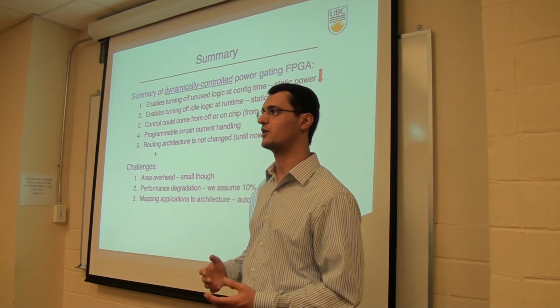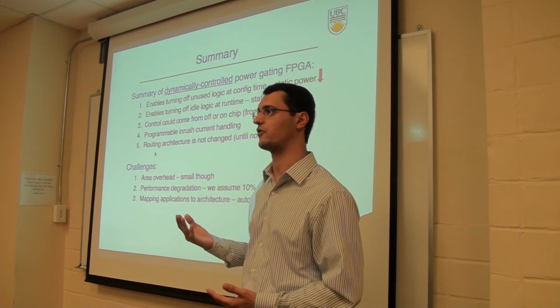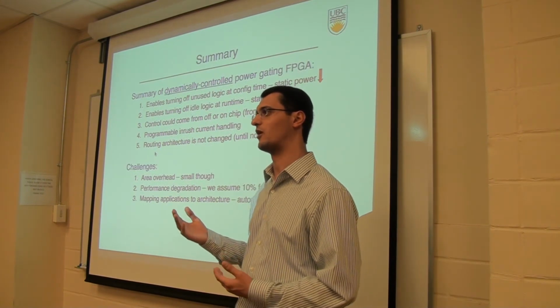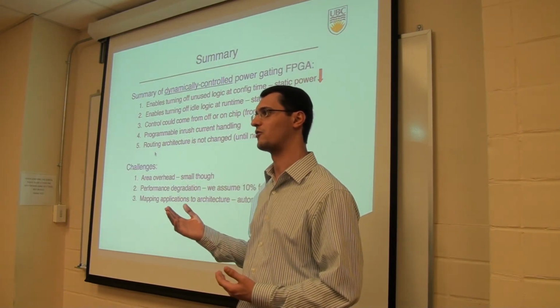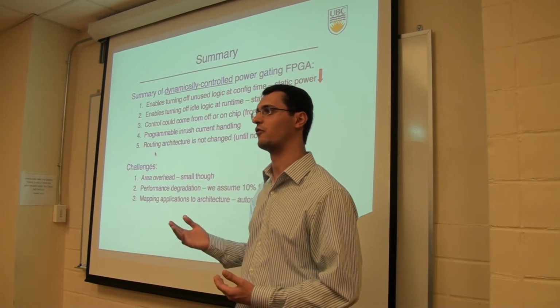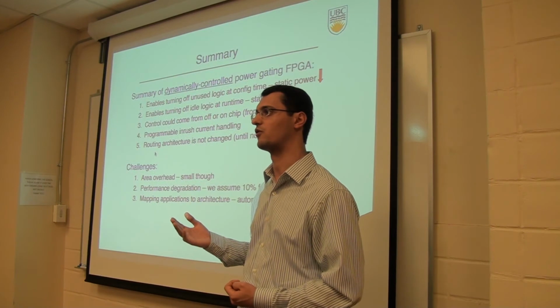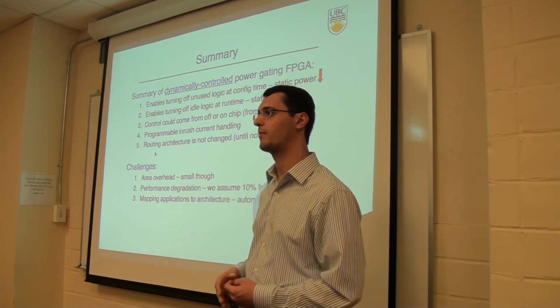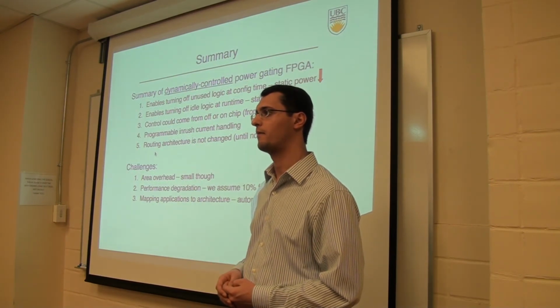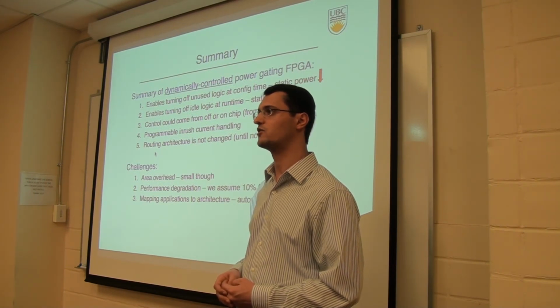So basically the power switch size will increase, right? We did iterative sizing for the power switches in order to get 10% performance degradation. Or are you assuming that if you double the region size, it will be less than double?